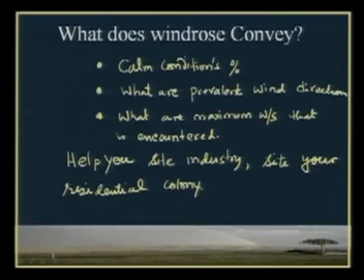Suppose the conditions are calm, then you don't want to have industry where the conditions are very calm, because if there is some problem, then pollutants will not disperse properly. So you have seen how useful windroses are. You can plot the windrose for 1 month, for 6 months, for various seasons, for the entire year, or for a decade.